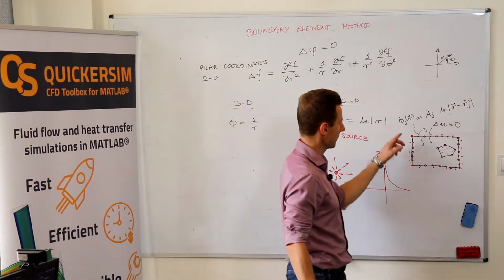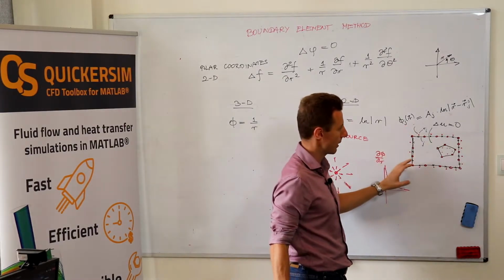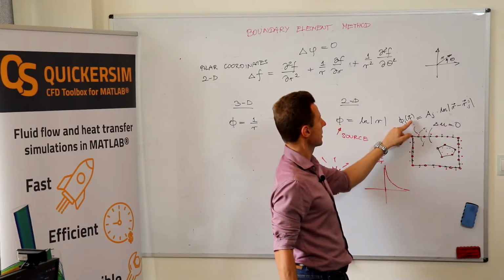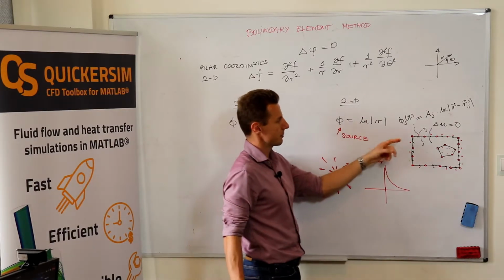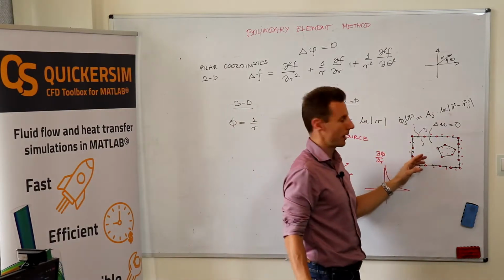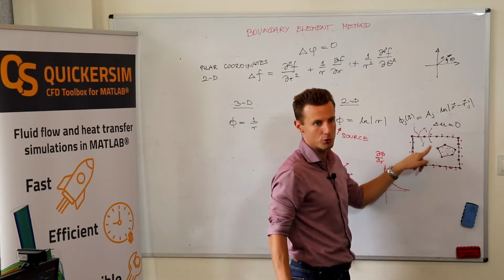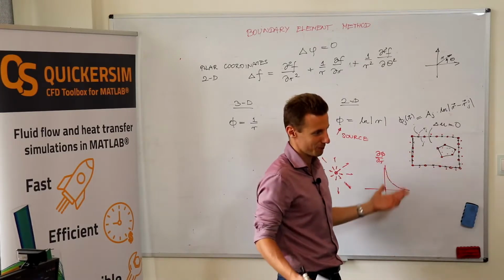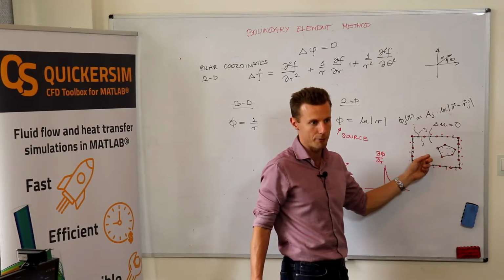So we've got as many phi j's as we've got boundary elements. Obviously, because you've got an explicit formula for phi, you can easily calculate the value of phi for whatever point you choose. It doesn't even need to be inside of the domain; outside it doesn't make sense, but you can calculate it everywhere.